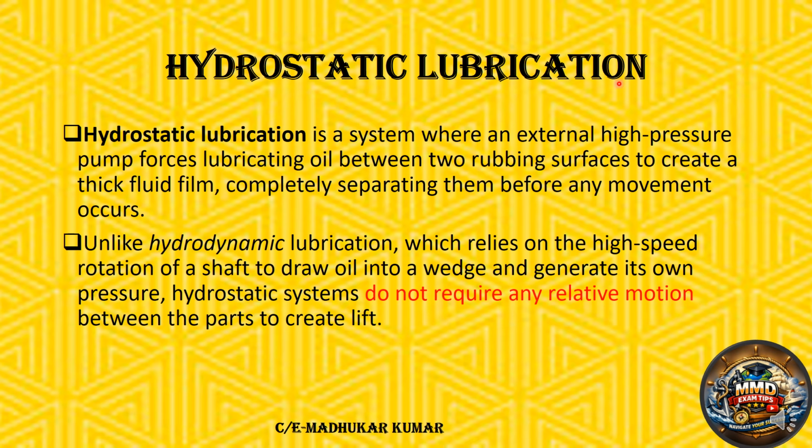Hydrostatic lubrication. So what basically is hydrostatic lubrication? It is a system where an external high pressure pump forces the lubricating oil between the two rubbing surfaces, to create a thick fluid film and completely separate these surfaces before any movement occurs.